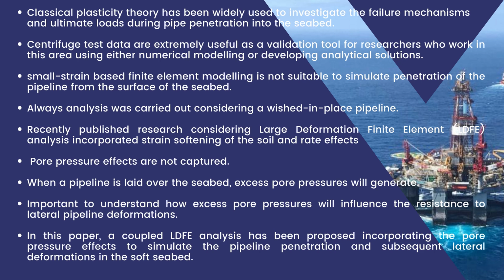In the small strain analysis case, normally the penetration is simulated from a wished in place condition. That means it is embedded at one point in a certain depth and penetration is continued from that depth. It is not from the ground seabed surface to the deeper depths. Recently published research considering large deformation finite element analysis considered the strain softening of soil and the rate effects, but the pore pressure effects are not captured.